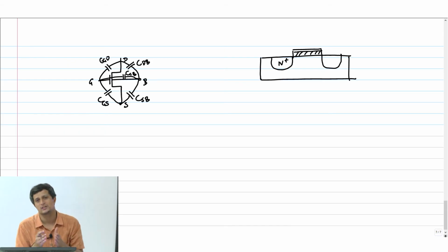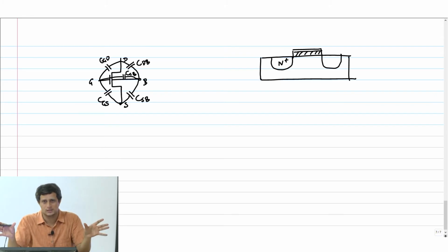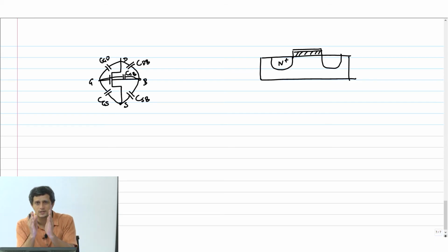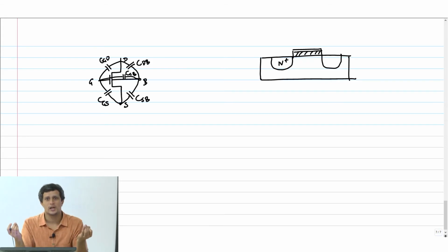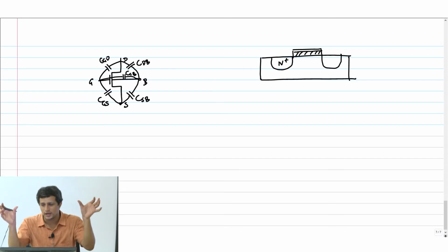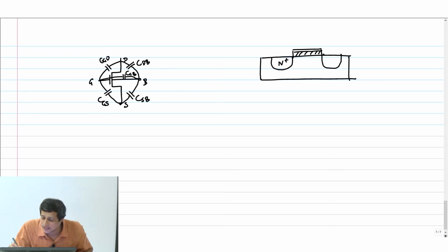This in fact is manufactured in something known as a self-aligned process. You grow the silicon, make everything silicon dioxide, then put a mask and harden one region and make the other soft. Then you etch out the soft regions. Because the gate oxide is itself acting as its mask, it is a self-aligned process, and typically I will get a nice diffusion region exactly like this.